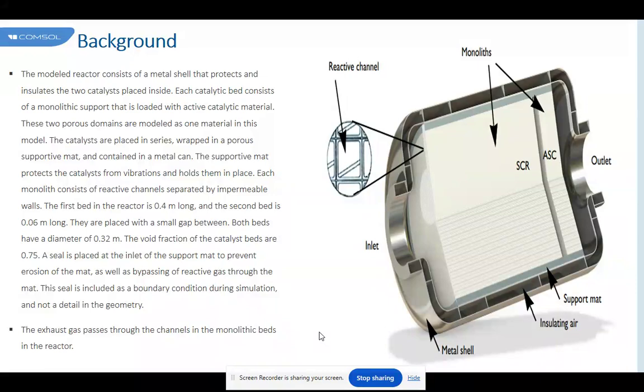Conversion efficiency is also affected by the cell density distribution of the substrate. This effect is highly correlated to the fluid distribution among the cases analyzed. It is found that a relatively small core inserted in a monolith with a lower viscous resistance increases the pressure drop and decreases conversion efficiency simultaneously. Hence, such a combination is highly discouraged. On the other hand, if the core has the lowest viscous resistance, then the pressure drop and conversion show a positive correlation.